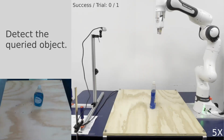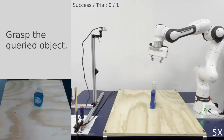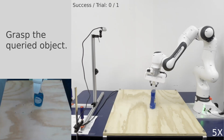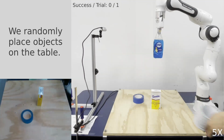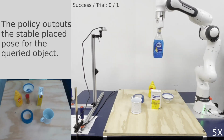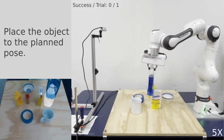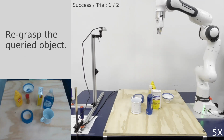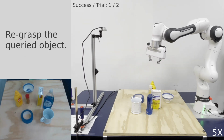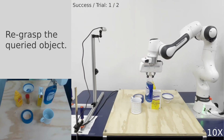In each episode, the robot arm grasped and lifted a queried object, while 6 to 8 other objects were randomly placed on the table to form an unseen clutter. The policy predicted a stable placement pose based on the scene points cloud captured by the camera, and the pose is then used to plan and execute the robot's actions. We repeated this process by randomizing the clutter configurations for 5 episodes in 1 iteration per object.